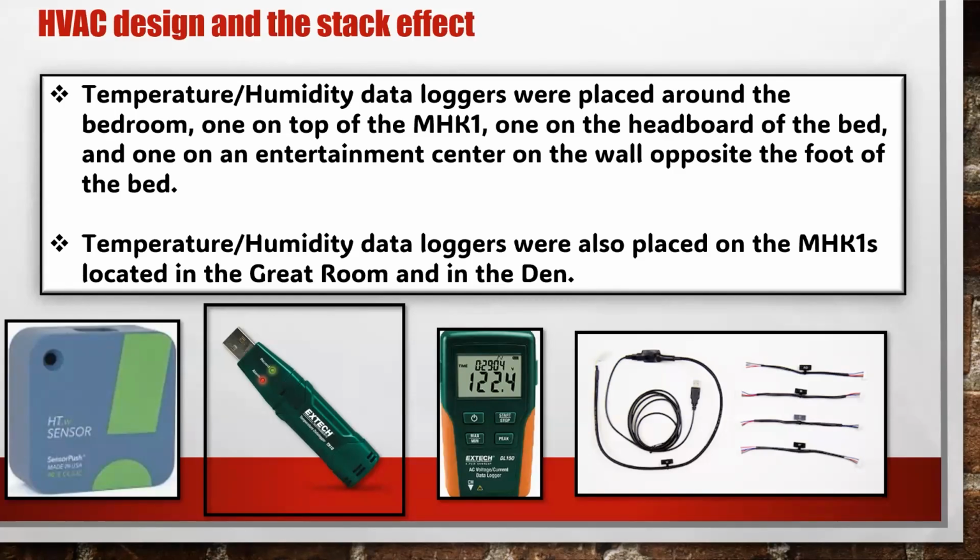Right. And again, it's all so that I could calculate BTU output. If I know how fast the fan is running and the CFM levels are posted in the submittal, there's no ductwork to worry about that would reduce the airflow. So as long as it's running in medium speed or high speed, then the rated CFM is useful for calculating that. But I need to know what speed that is.